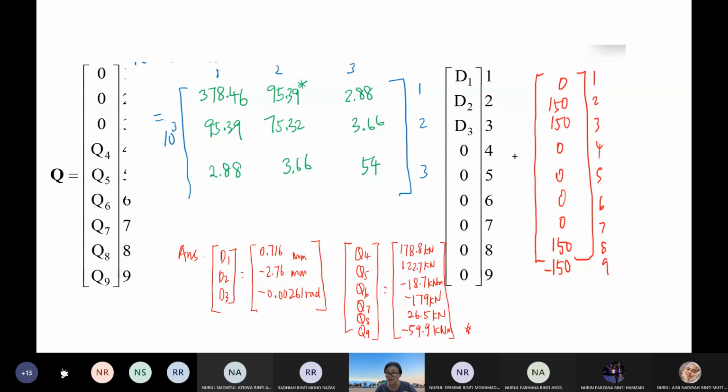Apply the support reactions into your real structure, then cut a section, and you can determine the axial force, shear force, and bending moment for the internal forces at all your elements. There is also a way using the stiffness equations, which I will cover in my next pre-recorded video.